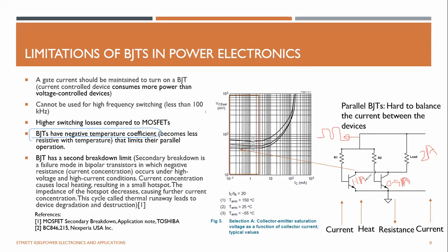So when this transistor drives a large current compared to this one, it heats up pretty easily compared to this one, right? So this current increases and the heat dissipation of the transistor increases, as you know, the power loss is this current times the voltage across the collector-emitter, right? So this guy is heating up faster than this guy.